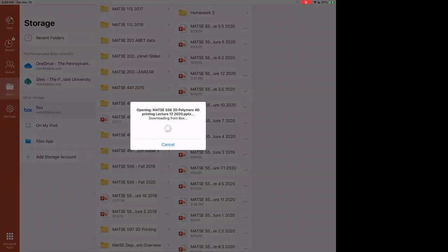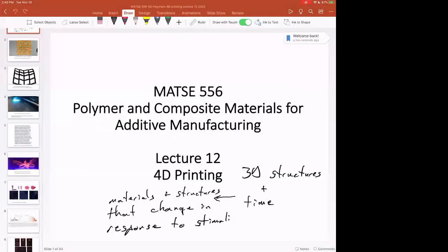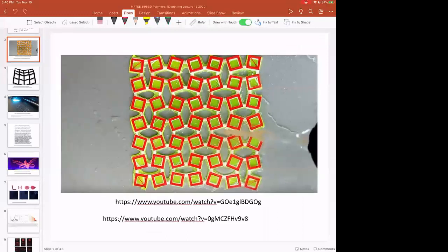And so, of course, you can make a lattice where the material expands when you add water, just like a hydrogel or something like that. But based on the design of the connections between all of the different cells, because of the metamaterial behavior, you can get this construction to shrink while absorbing water rather than expand. So it's sort of the opposite behavior, or it's an auxetic behavior from what the typical material deformation looks like.